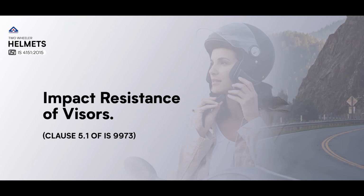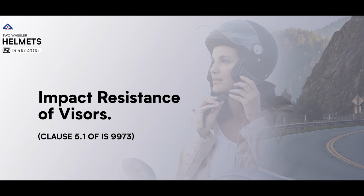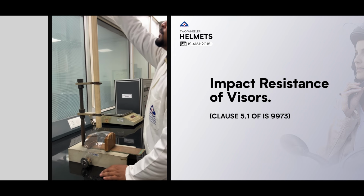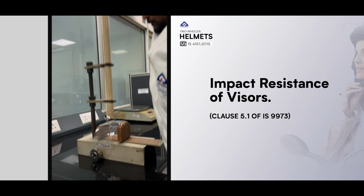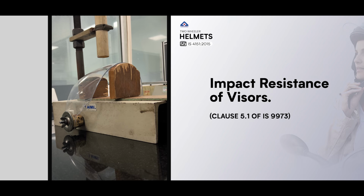Impact resistance of visors, Clause 5.1 of IS 9973. The impact resistance test assesses the visor's ability to withstand impacts. A steel ball weighing 50 grams is dropped from a height of 1 meter onto the visor at room temperature. To pass this test, the visor must not fracture or detach from its mounting.